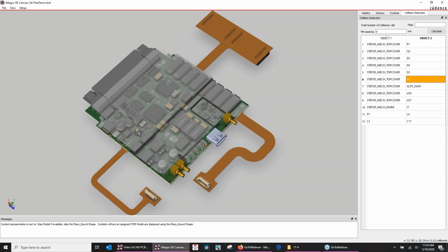So they're saying whether you call that a error or whether you call that a warning, at least tell me I got a push button switch underneath that pan that I don't have access to, just like the connector. So I thought that was a very good insight from the customer. We pass that on to Cadence. We're hoping for the next ISR release that they will have flagged switches underneath pans as not necessarily an error, but a warning to say you want to make sure that if you need access to this, you do not have it, the pan's covering it up.